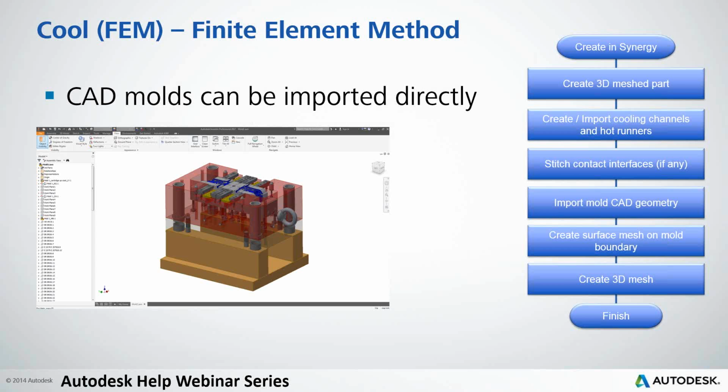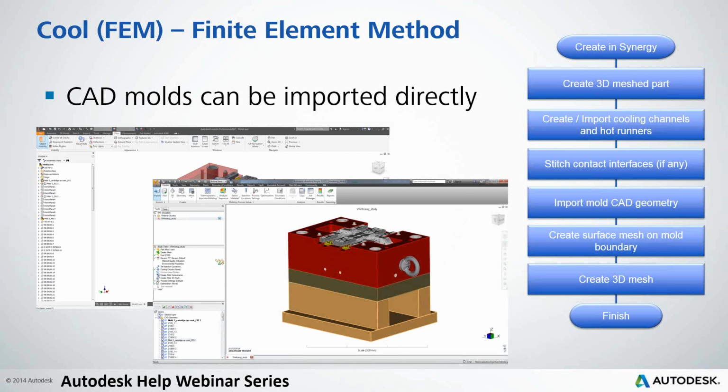And if we model here, in this case because it's an Autodesk product, we could import it directly to Moldflow. Then we need to define the different properties, we need to mesh, but we could bring such a detailed tool into Moldflow, and probably for the last simulation, let Moldflow calculate the real scenario.